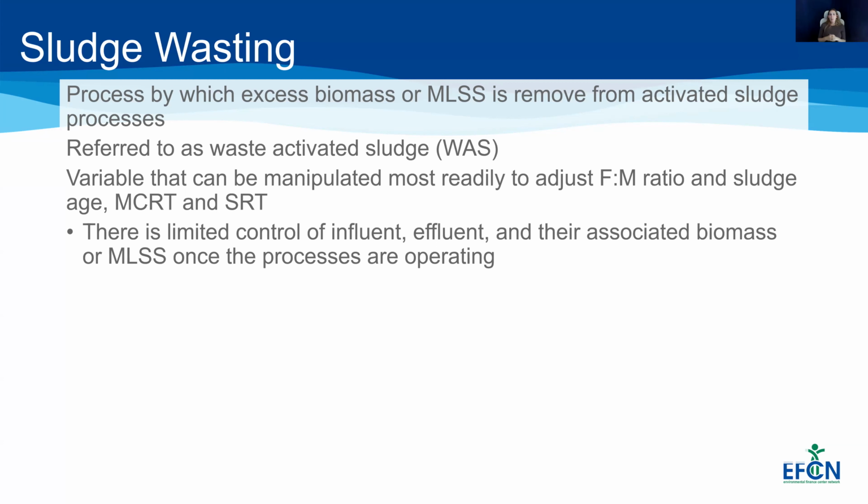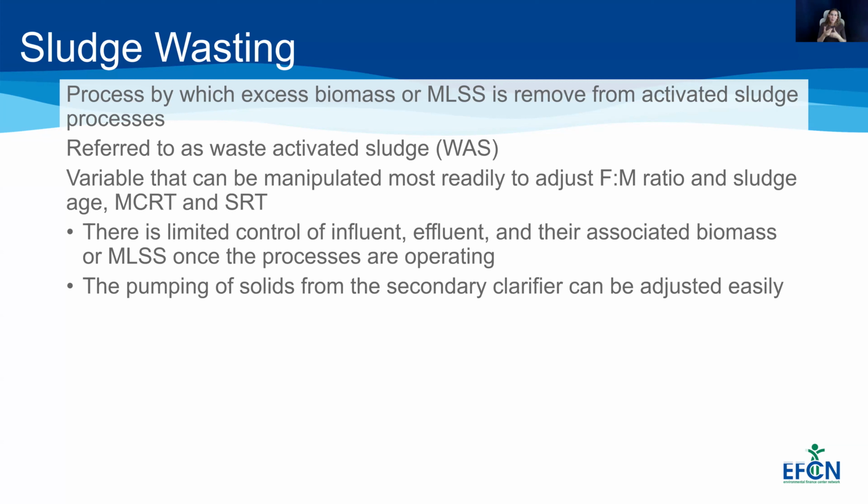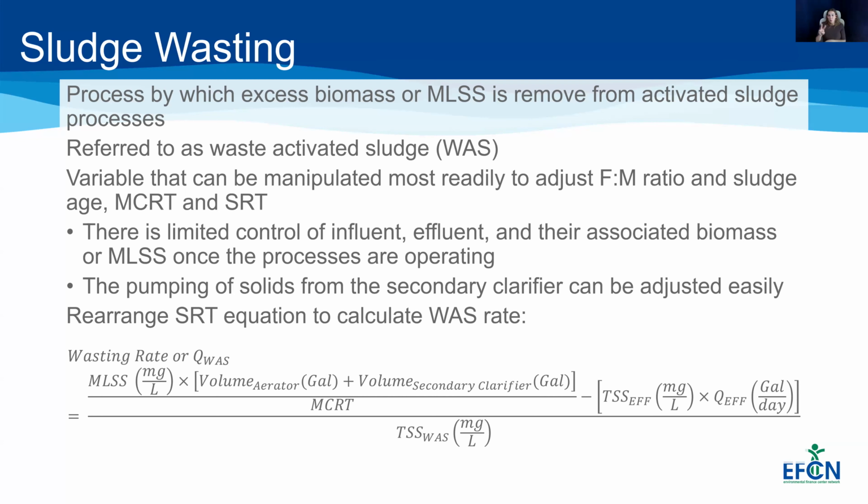We have limited control of how much influent and effluent we have and their associated biomass, but we can adjust how much we are wasting. And we can adjust that based on how much solids we're pumping from the secondary clarifier. We tend to rearrange our SRT equation to calculate those WAS rates, and that may look something like this.